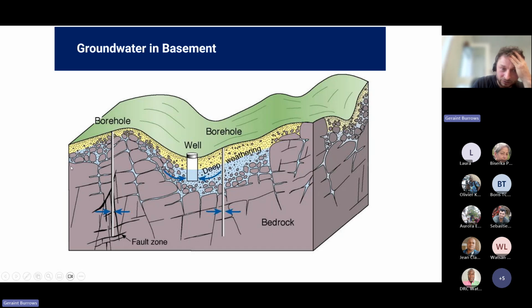If you've got a 100-meter spread, you're therefore going about 20 meters down into this material, and there's no scale here, but let's pretend that's about 20 meters. Then you'll be getting an average resistivity measurement taking into account the material around the 20-meter mark, and it'll be higher there than when you get to here, where you're going to have much less resistive materials.